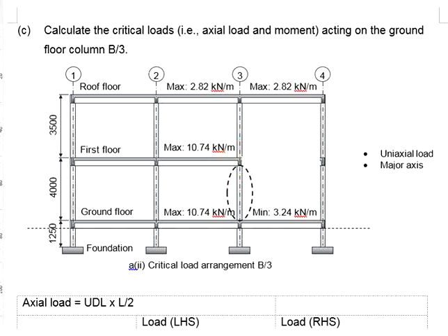The amount of moment taken by each member is subjected to the stiffness of that particular member relative to the total stiffness of all members connecting the joint.